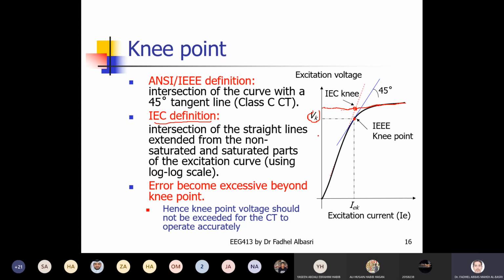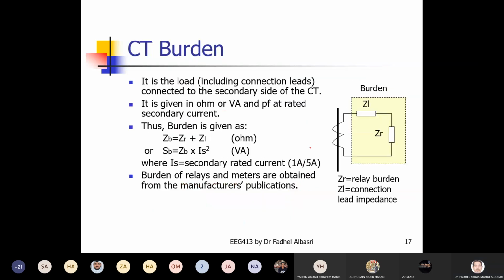So generally, the CT error will be excessive if you exceed the knee point. So we should design our CT such that we don't go beyond the knee point, to maintain the error small.